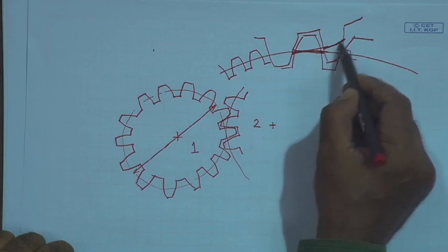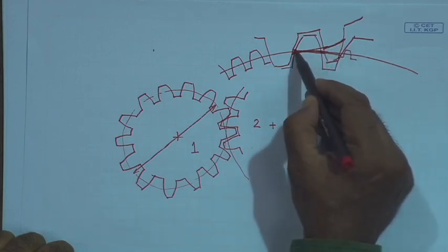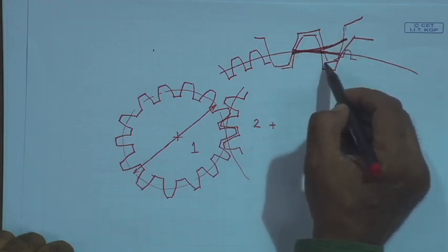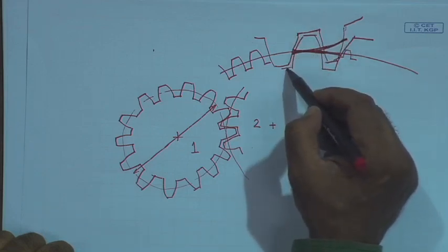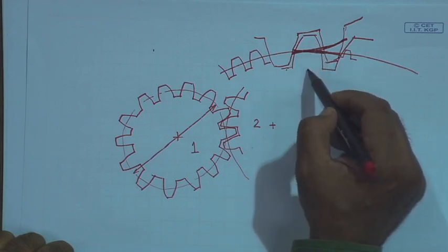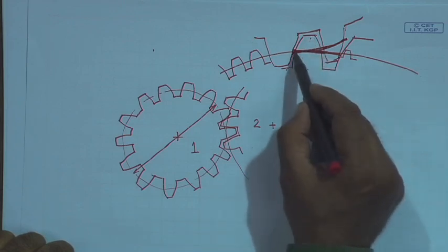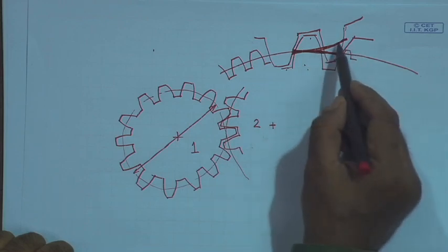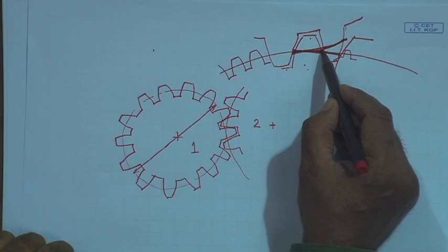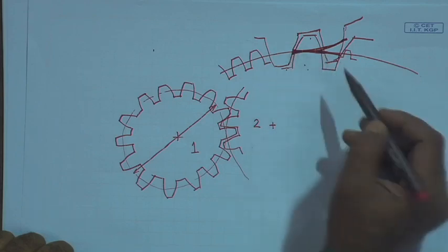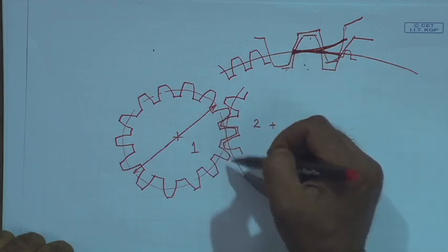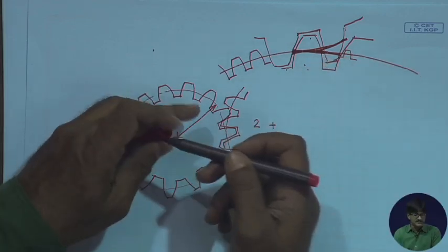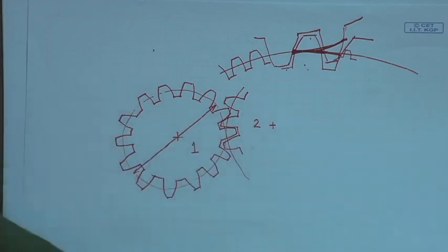Likewise, this one will have to be accommodated by that one, and immediately we come to a particular condition that the circumferential span of a gear tooth and its corresponding tooth space have to be the same for meshing gears. Basically, this plus this has to be equal to that plus that. Okay. Once we have established that, we come to a basic relationship between meshing gears. Let us have a quick look at that.